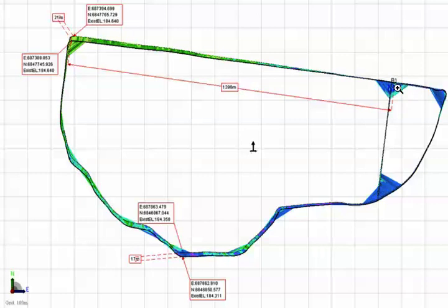And then we shifted both, we shifted the multiplane coordinate system so that the master benchmarks lined up. The GPS Ag system saved the coordinates in eastings and northings, you can see with this large number here, and using the GPS datum ellipsoid. So we shifted the multiplane so that they matched up at the master benchmark, and then we wanted to see the difference at the extremities, and as you can see